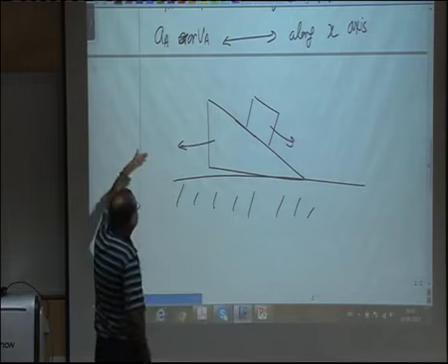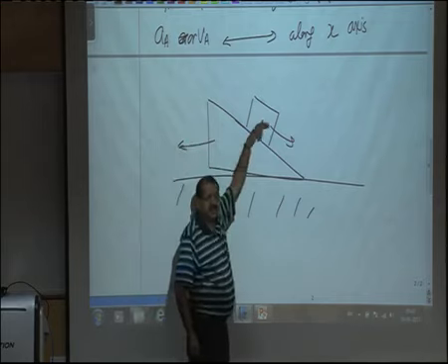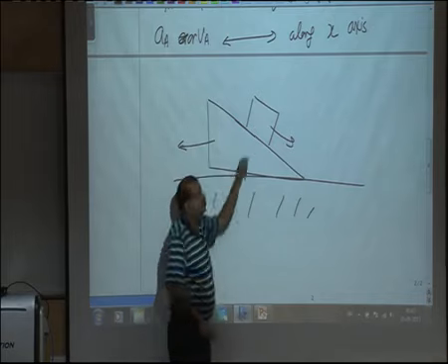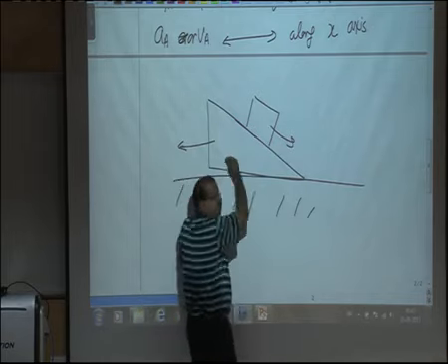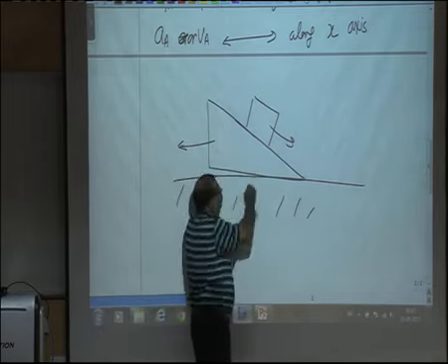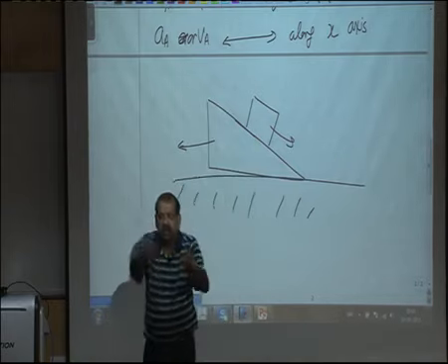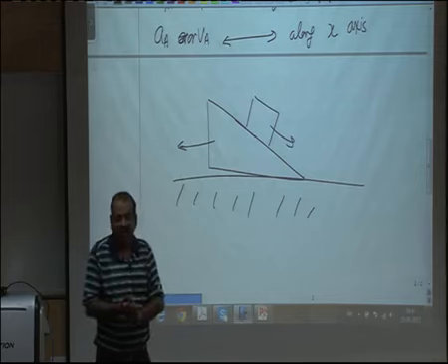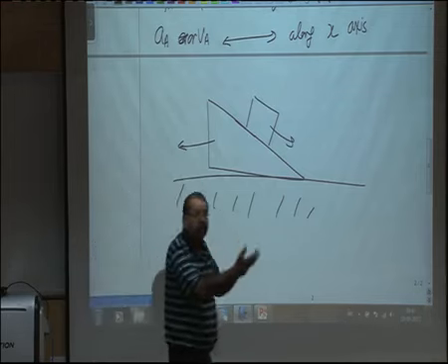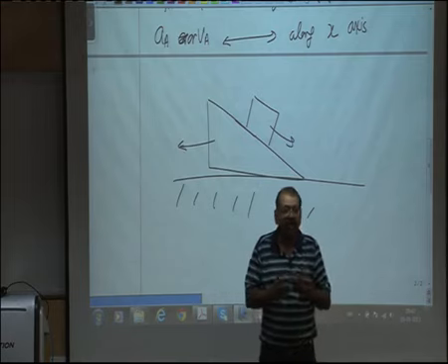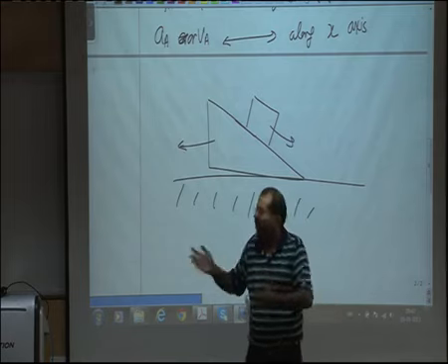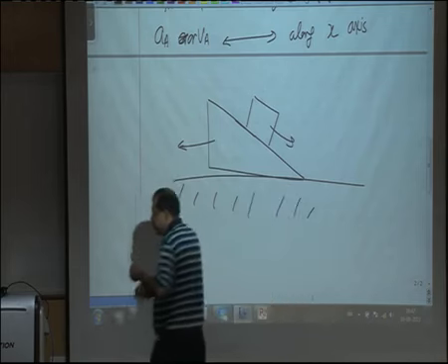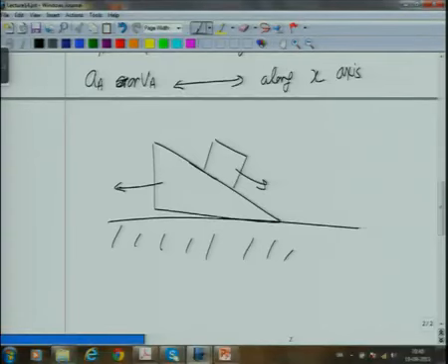But if that is the case, then I know acceleration of B. So, the absolute acceleration of B will be a sum of this acceleration and this acceleration. So, it will be directed somewhere in between these two. You have to add these two, and that will give you the acceleration of B, and to that you will use Newton's law. There is another way of solving such problems, pseudo force, but I will explain what pseudo force is, and we will come to that. So, this is how these things could be worked.